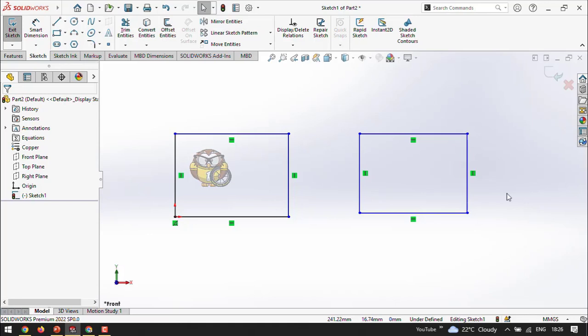I'm waiting for your answer. Yes, sir. Now you see the understanding. Why is the black color line showing here? Why don't we have the black color here? Because of the XY, yes, due to the origin point. Also, one important thing: when you complete your 2D sketch, it should be black. It means all constraints and all required dimensions are applied in your drawing; only then does the drawing color change to black. Otherwise, it is blue only.